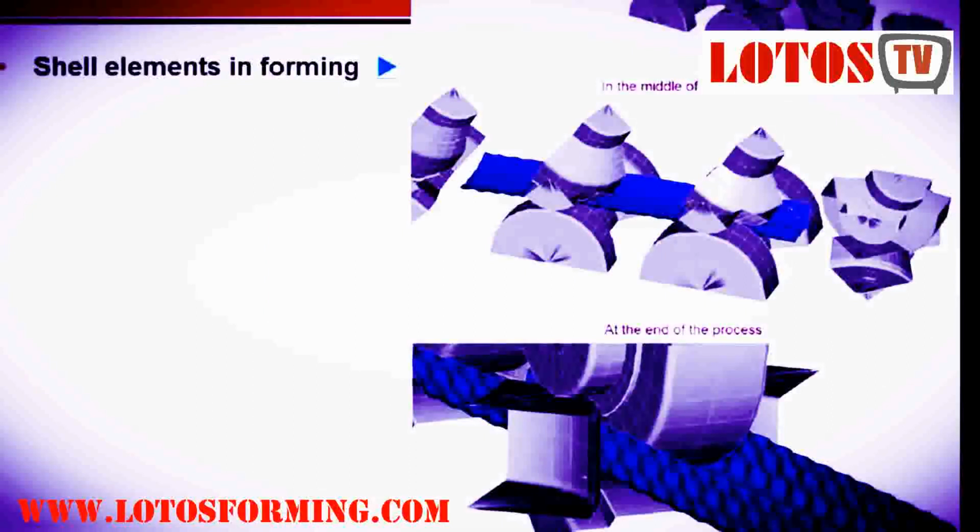Here I show you an example of how we perform the cold roll forming process on the dimple strip that we generated from the previous step. You can see on the top is the flat dimple strip made using the shell elements approach, and then this strip goes through a series of rolls arranged in tandem, as you can see here.